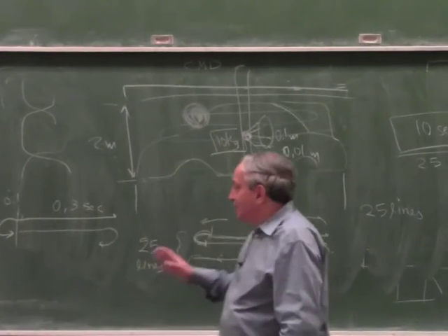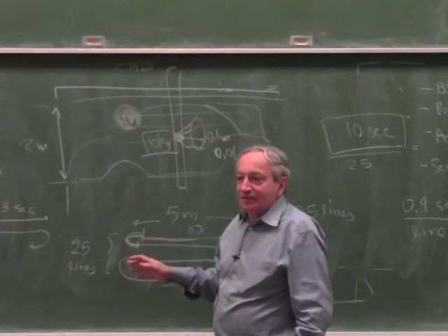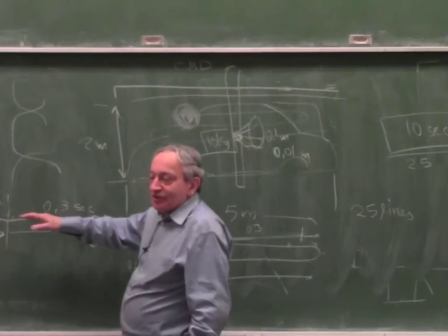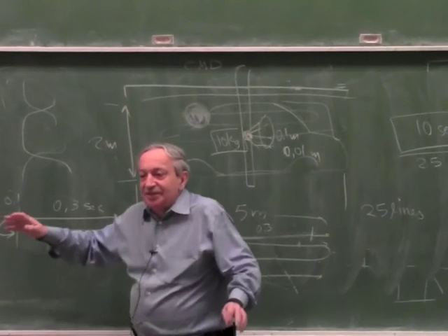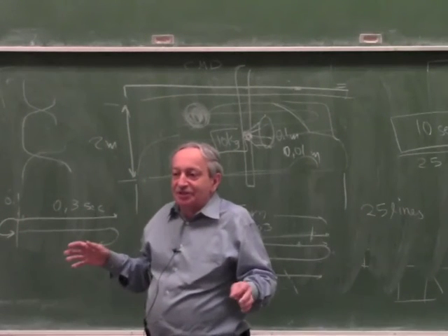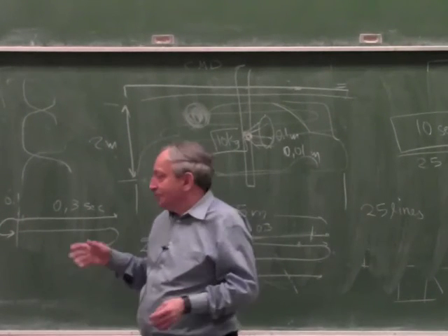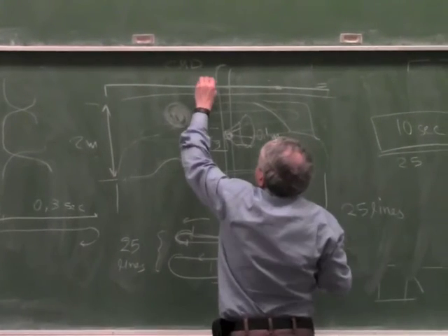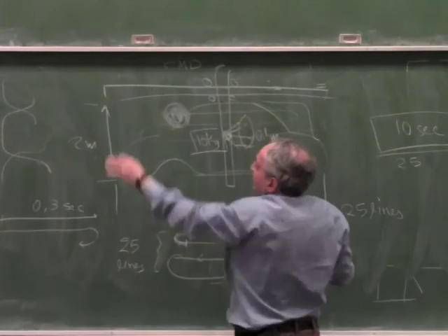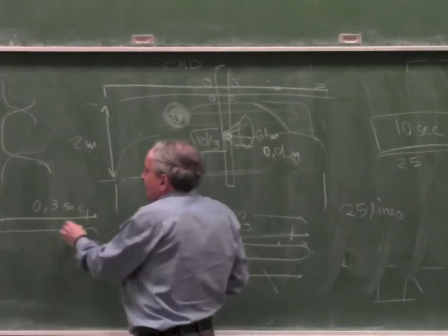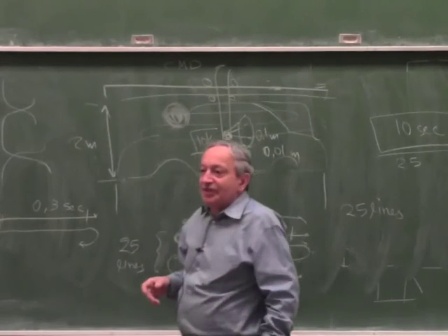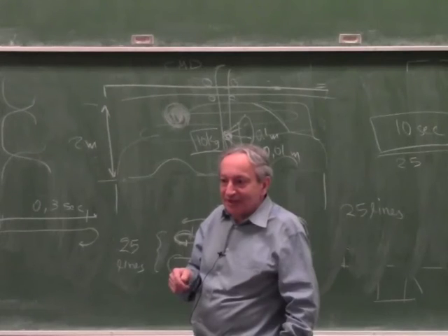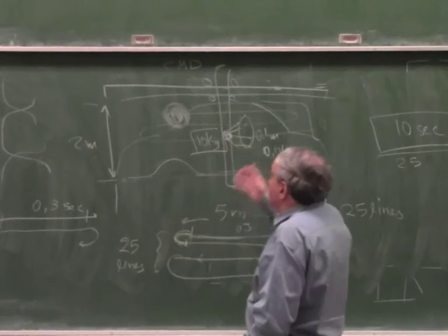Okay, so is this clear so far? Good. So during the linear travel, if it's constant velocity, in theory there is no power needed, it's just to overcome friction. But constant velocity, and if this runs on some nice rollers, it slides. So this part is of no interest. It's just of interest if I use a motor, I have to check what speed the motor has to run. Because at the end I have to suggest an actuator.